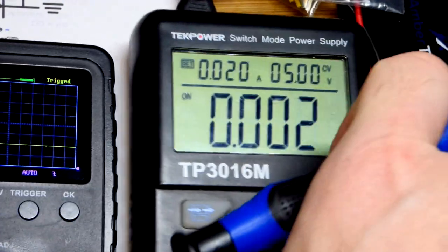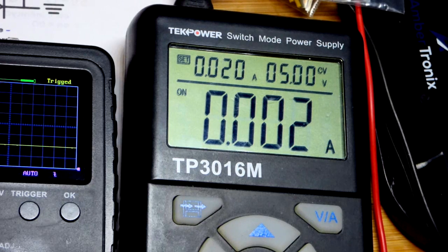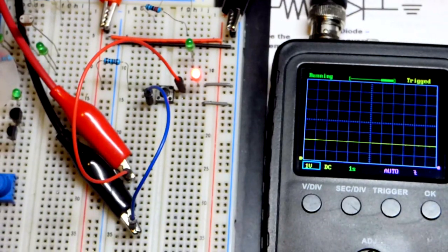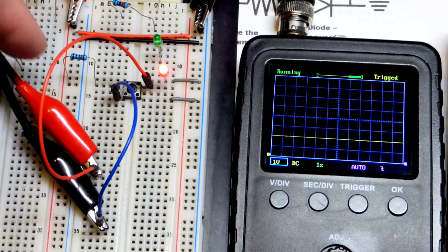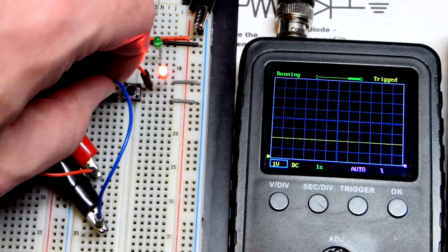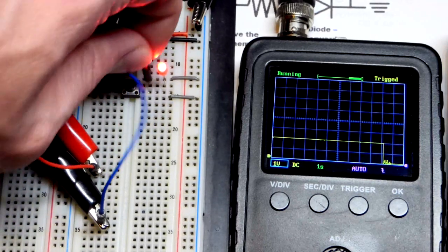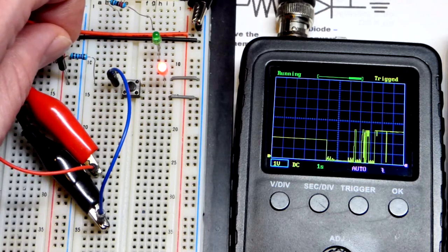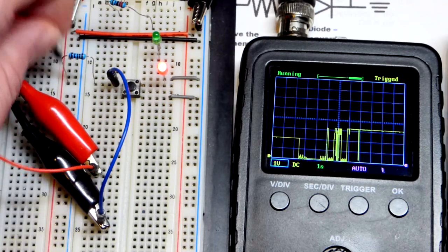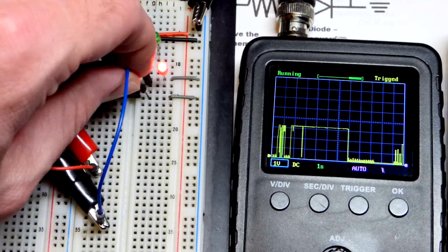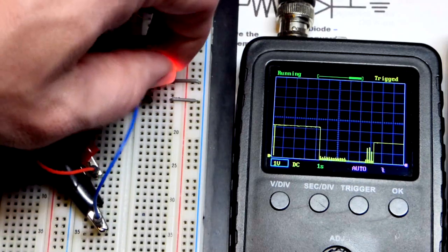We're dealing with 5 volts at the supply. We're getting about 2 milliamps of current right there, approximately. It's probably actually 3 milliamps, but it's about a milliamp off because that's a 1 kilo ohm resistor. If the LED is blocking 2 volts, then we will have 3 volts across this resistor, which again, we can look at. We'll go up there and then across the resistor, and you can see 3 volts. So it's actually probably 3 milliamps of current, but we're not being too picky right now. Now, we'll put those back. We got the 2 volts for the red LED.